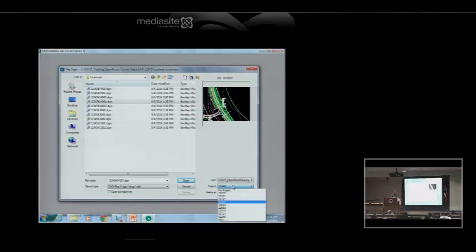One of the other things that is different here is I have multiple projects instead of just one project. ODOT has traditionally not used the MicroStation PCF file, the project configuration file. ODOT has traditionally used the PCF really as a site configuration. So in the past, you always saw ODOT V8I, ODOT V8I, if you used an ODOT installation and followed what ODOT did. I know some firms, particularly larger firms with good IT support, have set up their own way of doing it.